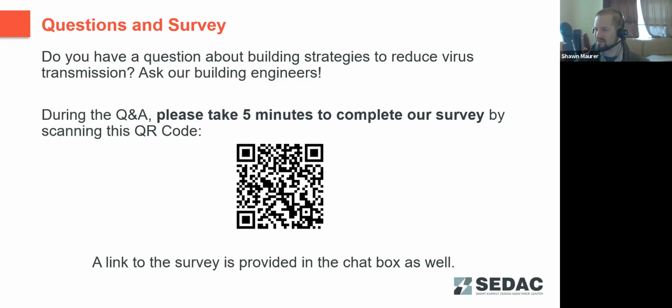Again, noise is going to be a bit of an issue from having units in the room. You can get units that have limited decibels of sound emissions that are designed for classrooms. You can also control when they're in operation. During lecture periods, you might be able to turn them off when just the teacher is speaking, and then turn them back on during quiet periods of the classroom, study periods, or whatever may be the case.